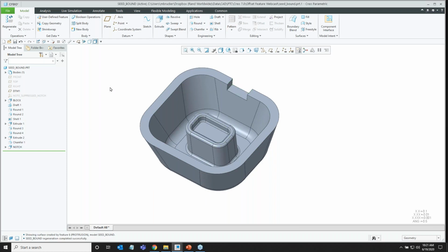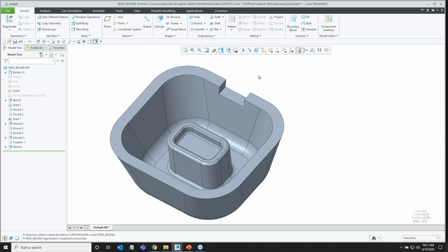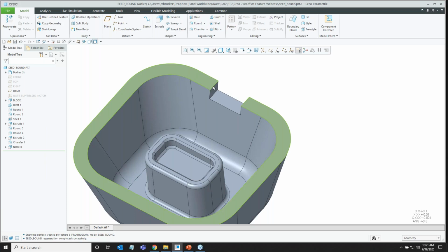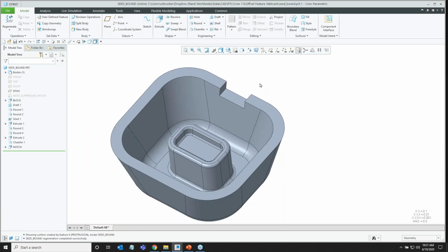So now, if I'm trying to pick all those inside surfaces, I actually need 4 boundaries now. I would need this surface as well as the 3 surfaces of my little notch here. I'd have to pick all of those as my boundaries. So to do that, I just pick 4 boundaries in this case. So I'll start with this surface. Maybe I don't notice the notch.